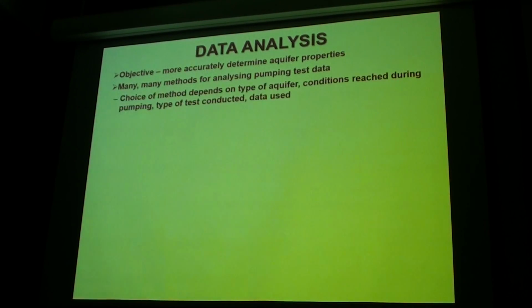It'll give you all sorts of different people's names and dates that have come up with different means of analysing data from a whole different range of conditions, because it'll depend on the type of aquifer you've got. Right? Whether you've got a confined, unconfined, or semi-confined aquifer, the conditions reached during pumping, whether they reach equilibrium, right? Whether they're transient, when you turn the pump off. Okay? The type of test conducted, so whether it's a step test, whether it's a constant rate test, whether it's recovery data, okay? All those kinds of things. Whether it's a long-term or a short-term test, whether it's early or late-time data.